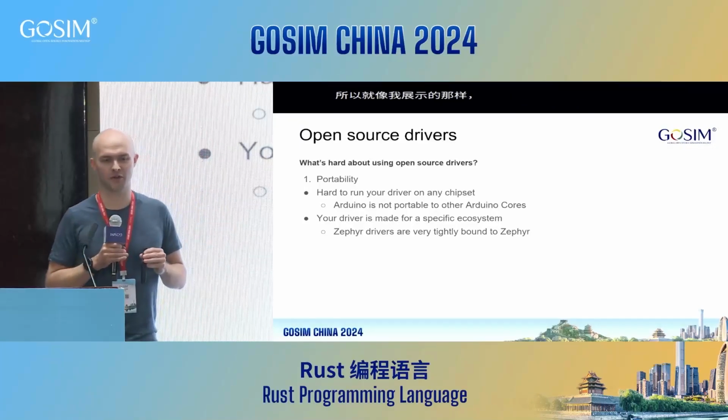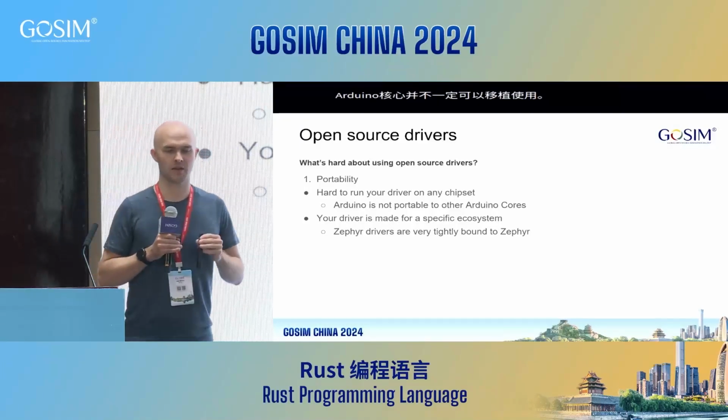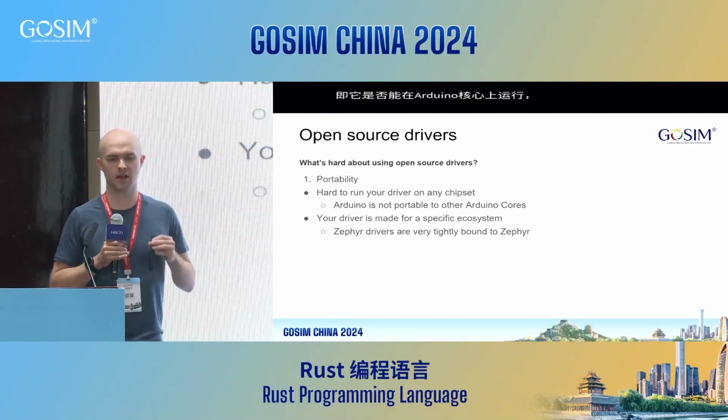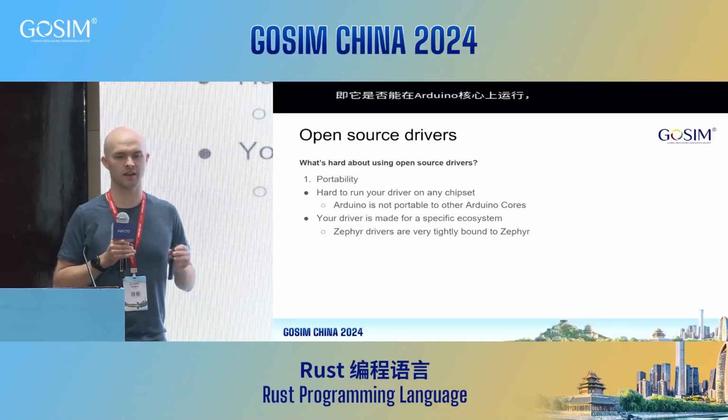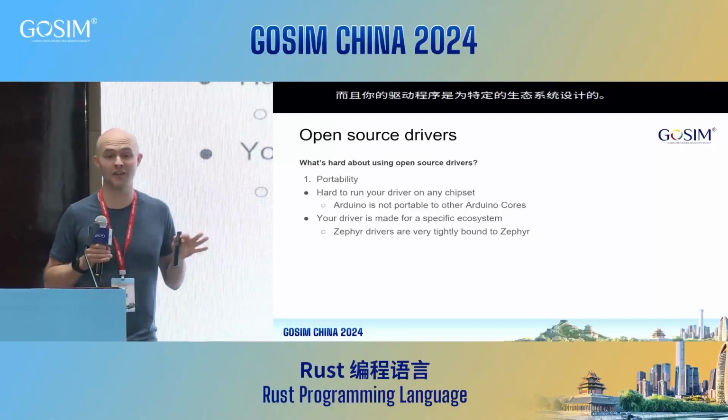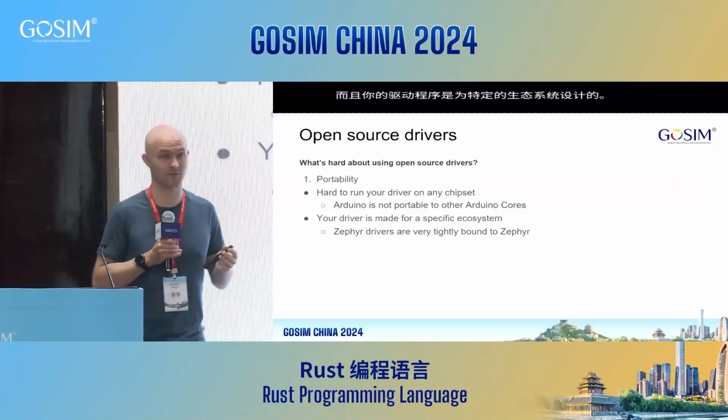And also your driver is made for a specific ecosystem. So I did not show this, but Zephyr drivers are very tightly bound to Zephyr. Aside from the struct definition, internally it probably uses some threading operations, say for example, that are specific to Zephyr. And I don't have those definitions in any other platform.